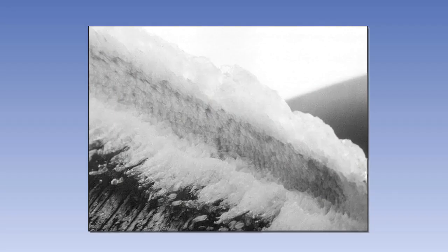The first effect that they have is to disrupt the airflow over the wing. This results in an increase in drag, but, just as importantly, a reduction in the lift force. The second effect is that the contaminants will increase the weight of the aeroplane, and therefore increase the stall speed. The combination of these effects is such that the takeoff distance required will dramatically increase.